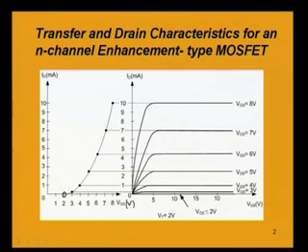So, for VGS equal to 4 volts, say, we are extending this drain current, which is the saturation current, beyond this axis, and it is extended, it is meeting the 4 volt gate to source at this point. Similarly, for 5 volt VGS, this is the point where the saturation drain current is meeting the corresponding gate to source voltage of 5 volt.